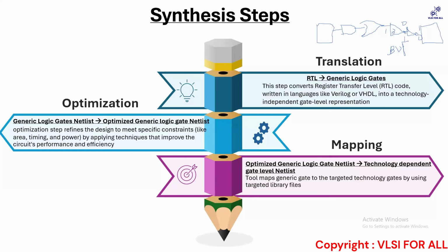Okay, they will do a comparison between your synthesized netlist and, for example, let's say their placement activity is being done. So the placement netlist is being done. So they can do it between your synthesized netlist and placement netlist. Now let's say that has passed. Now they have gone to CTS stage. Okay, they can do a comparison between placement netlist and your CTS netlist.